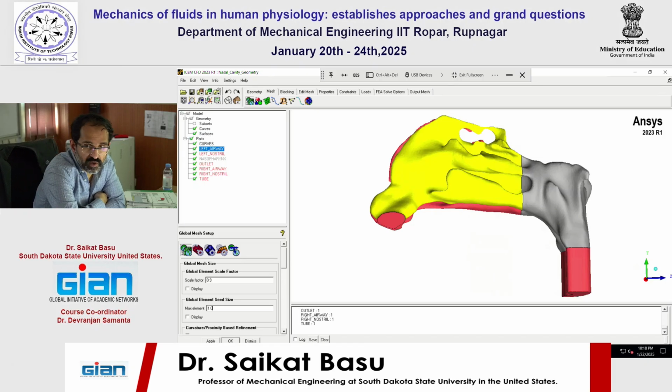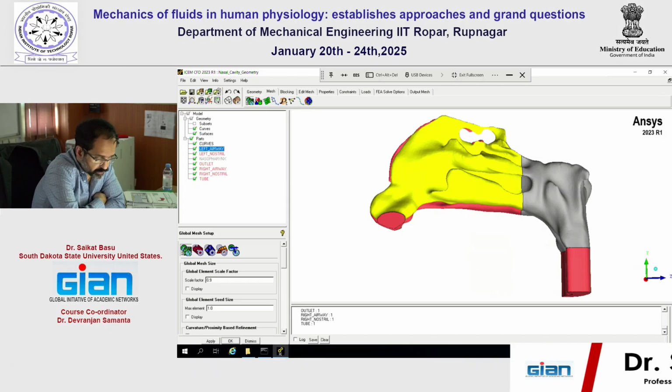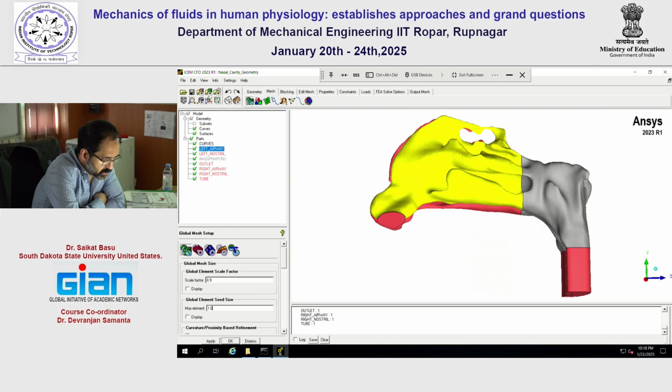So what do I mean by 1? Typically, the scale would correspond to a millimeter, right? But don't assume that every element here would be 1 millimeter, because that is not tenable. Whatever settings you introduce here, you need to still keep track of how many total elements are being generated and what the overall volume is, which would give you the mean size of each element.